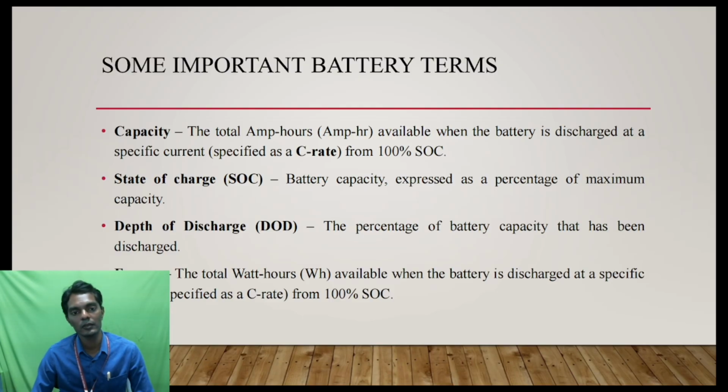Let's say my battery capacity is 20 ampere hour, but I already used the battery for 1 hour supplying 10 ampere. So how much is left? 10 ampere hour is left, because it can supply 10 ampere for 2 hours. I already used 1 hour, so for another 1 hour my battery is able to supply 10 ampere.